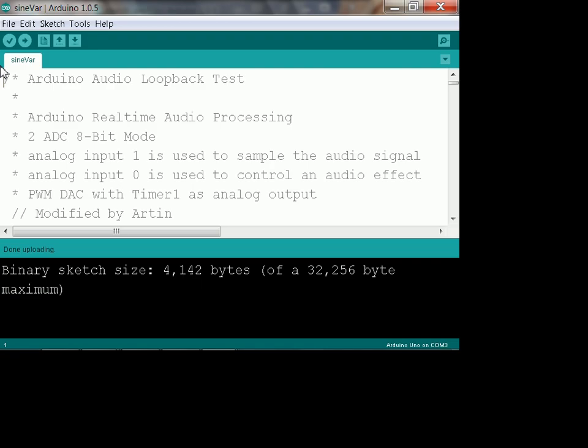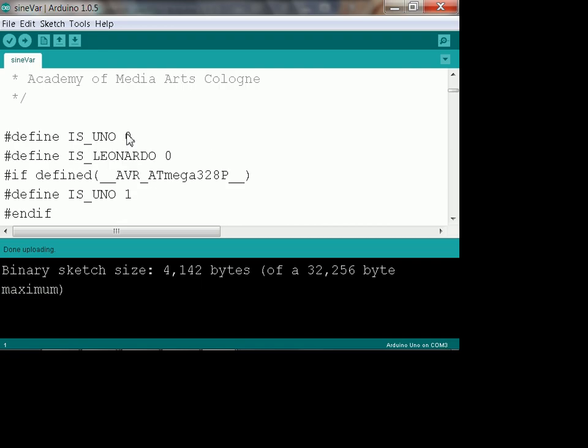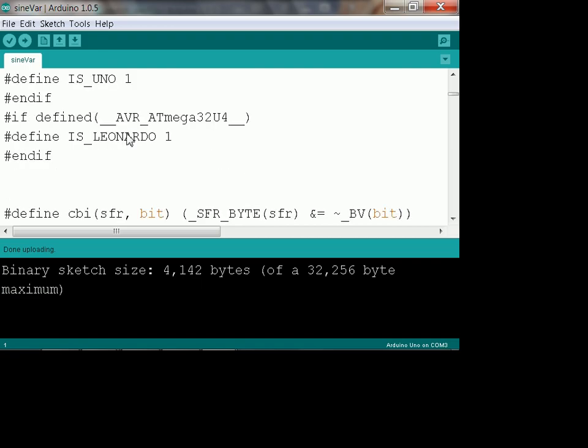Your basic idea here is all you're going to do is modulate the duty cycle. Duty cycle is generally defined as the percentage of the time in which something is on versus the amount of time in which it is off. So a 50% duty cycle means it's on 50% of the time and off 50% of the time. Similarly, an 80% duty cycle means it's on 80% of the time and off 20% of the time. That's simple enough, right? So if you can vary the duty cycle with precision, then you can have a very precise DAC. They call this a PWM type DAC.